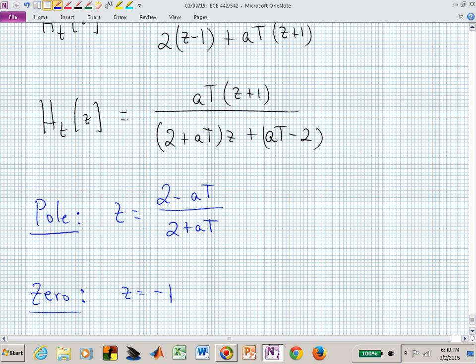That's on the unit circle, and that's really as far as we can get when we think about our frequency variable in the z-plane. If we were walking up the imaginary axis in the s-plane, that's the omega, that's our frequency response. Now we're moving along the unit circle, and the furthest we can go is to -1.